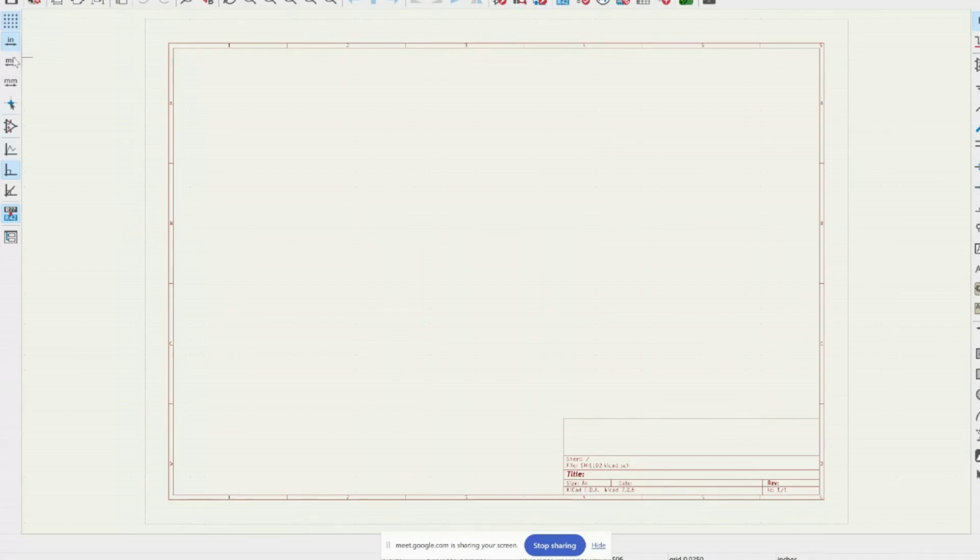The next thing is that the units are here. So you can switch between inches, mils, and millimeters on the fly. Other programs don't allow you to do that. They're actually quite cumbersome. They will actually insert rounding errors and kind of mess up your design. I've had that happen before. But KiCad, I've never encountered it. It's right here on the side. It's super convenient, especially not necessarily in the schematic, but in the PCB design phase. You might get a component that is given to you by the manufacturer that uses metric units, but then on the same board you have a component that's in English units. So you need to swap between the two in order to sort of see if the design is correct, right? So anyway, that's very convenient. I wanted to point that out.